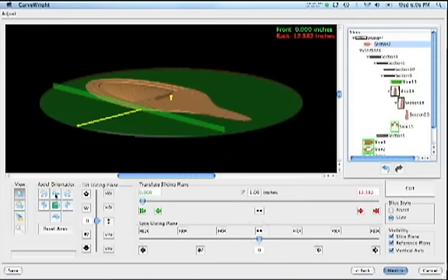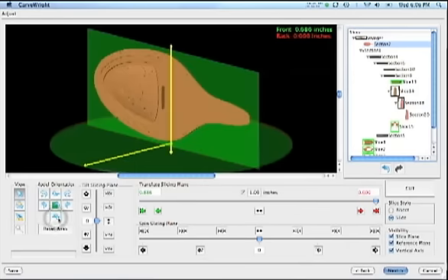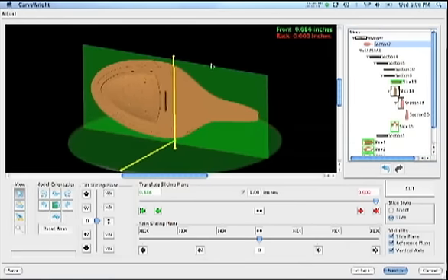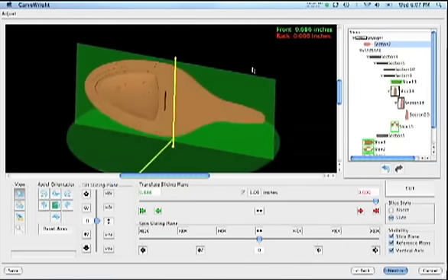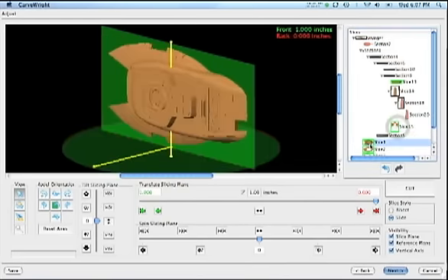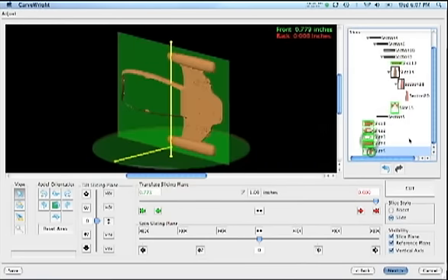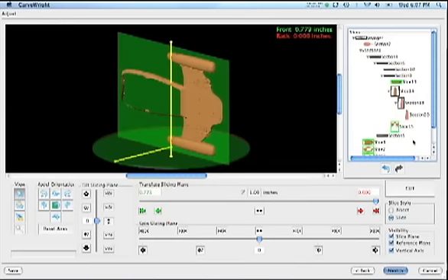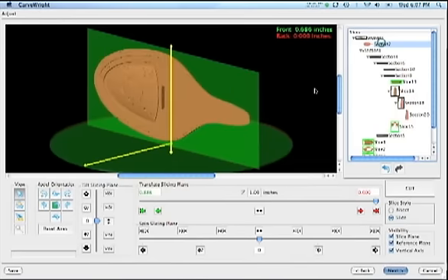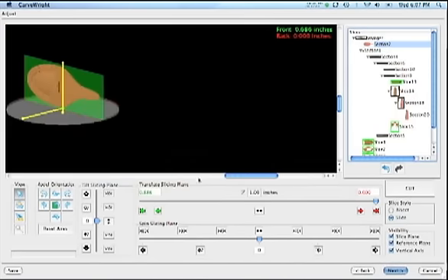So basically what that's doing is setting your Z so it knows I'm going to carve down onto this. Otherwise, if you've got it as a side profile, it'll take this whole thing and it'll just try to carve the profile of it. So I've got all my slices now, and there's not too many of them. We're under 20. We'll find out here when we go to the next section.